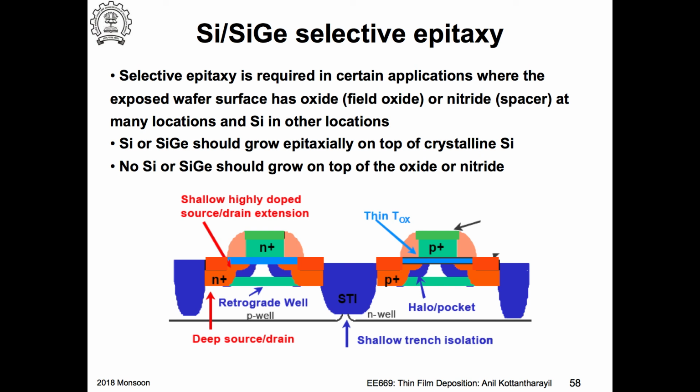So this is some technology, will not go into the details. So I have by some means from prior processing some oxide on top. Okay. So I'm going to mask this area, right? I would etch this, okay, and then I will grow silicon germanium. Okay. So that is one process.